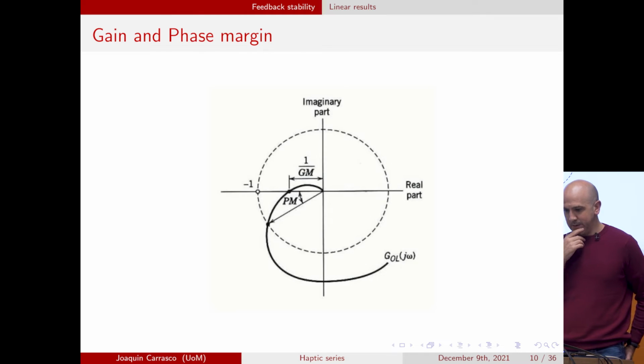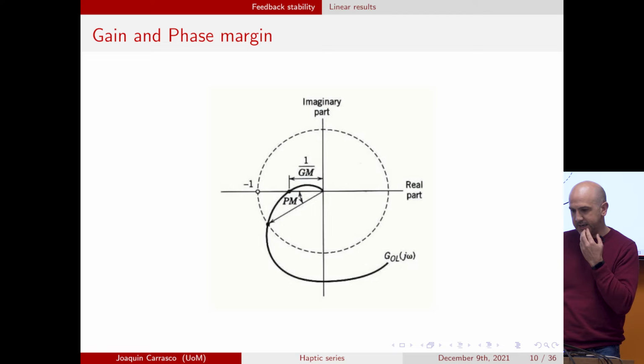But yes, we can come back later to this. How much process time delay will affect the amount of lag that's in the system, and this is showing you the lag that you can accommodate. Exactly. I am just trying to speak about delay, because we are going to be speaking a lot about delay. But yes, any lag in the system, anything that produces a lag, will move you to the -1. All right, thank you. Any other question?